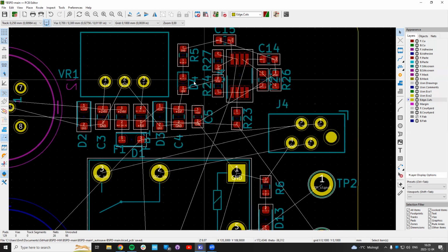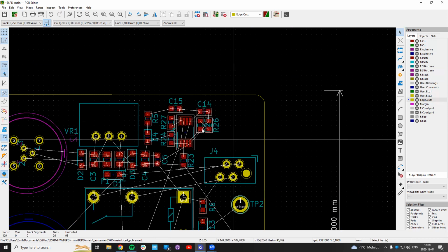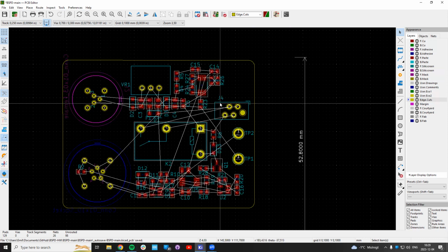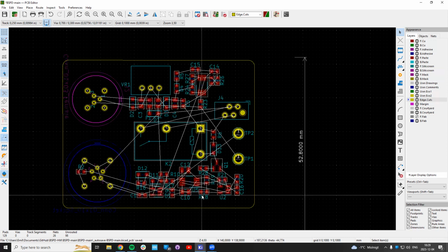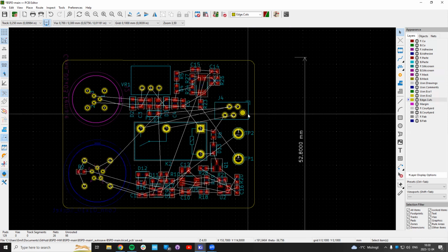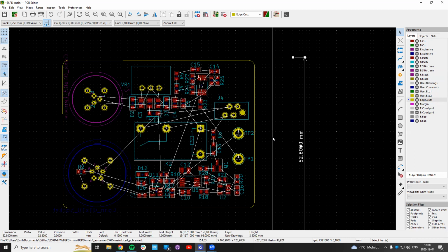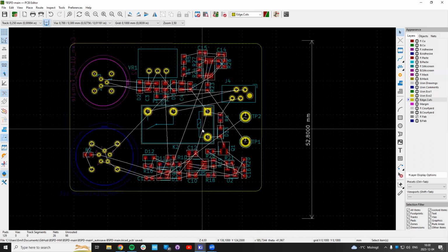And then we're kind of happy about the placements here. We see that this could probably move to the left. Do we need to? Not really. This side of the board could be cut off. So there is certainly a way to place more components up here and make this PCB a little bit tighter, but for now, no, since it's a bit uncertain about this one. As I said, this is a very small PCB. I think this is an okay size.